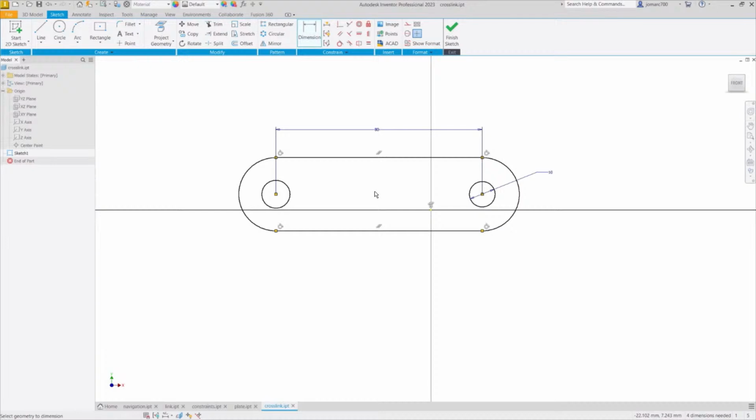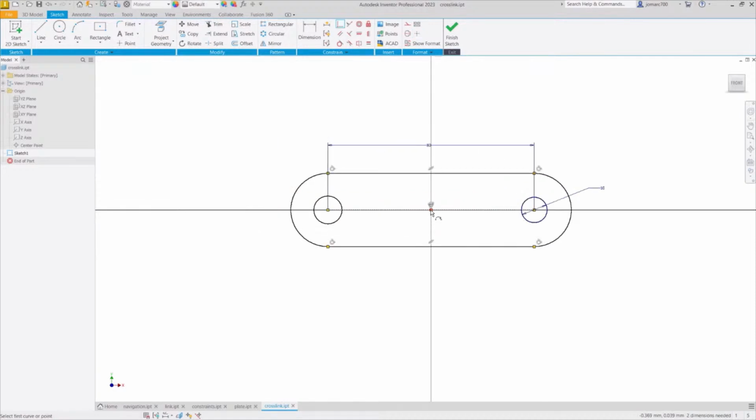And lastly, I want the center point of our sketch aligned with our origin. I'm going to create a line instead, creating a line from the center point to the center point, turning this line into a construction entity, selecting this, right click, selecting construction, and finally heading up, selecting coincident, selecting the midpoint and our origin, hitting escape.